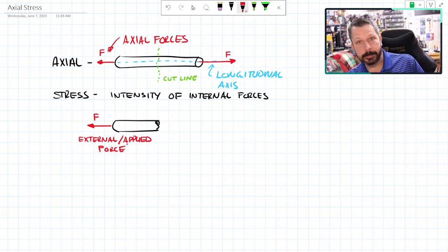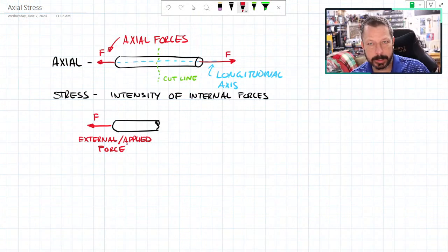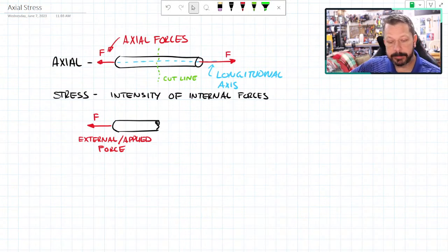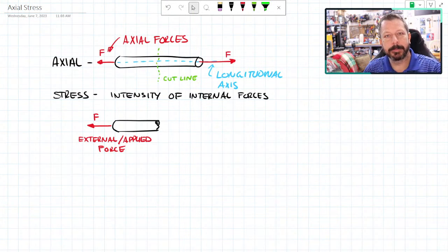And it's axial. It is an axial, external, or applied force. And for this little piece to be in equilibrium, I need to have this external force balanced out. Right? Because if I look at this free body diagram that I have on the screen right here, the second one, then that piece is accelerating off to the left of the screen, which would mean it's coming apart from the rod, because the rod is not accelerating.